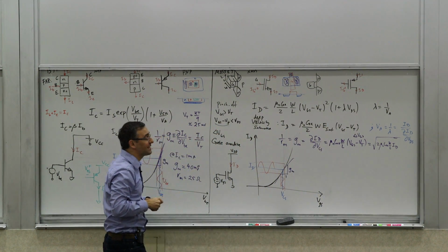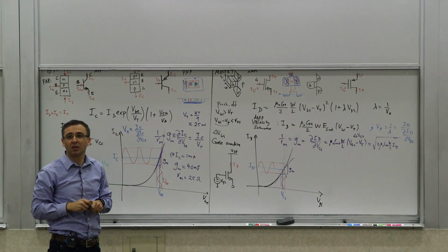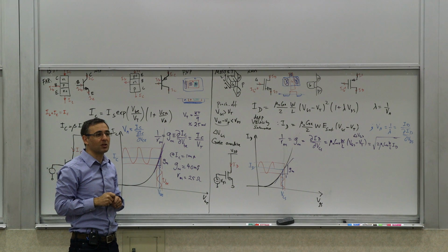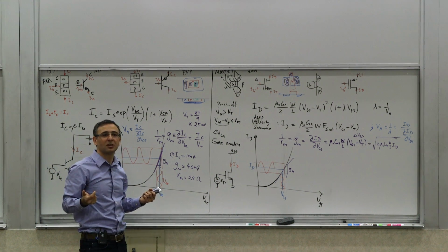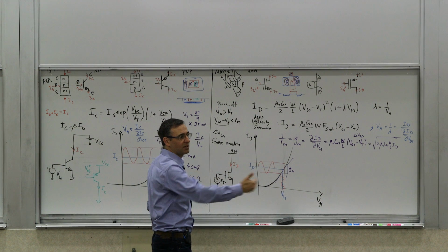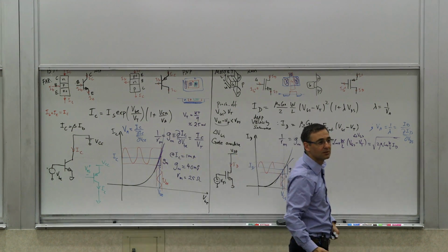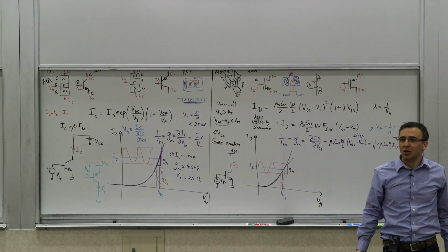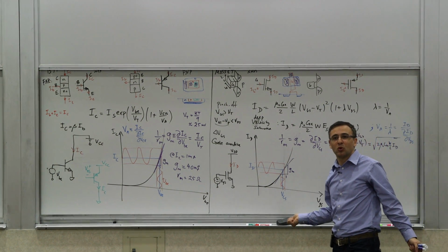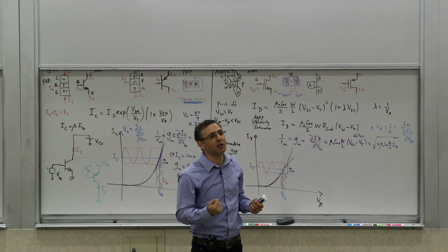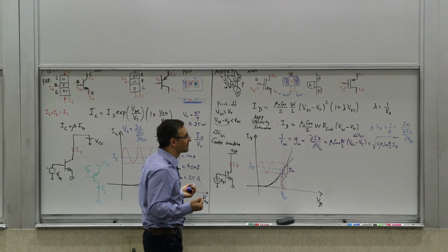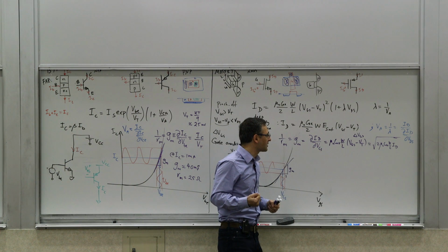So now you can see it doesn't even depend, in deep velocity saturation, on the VGS. So the operating point is not important because you're already velocity saturated. So transconductance is fixed by the maximum velocity, the saturated velocity or the saturation field that you can get. So beyond a certain point, if you get more overdrive onto it, you're not going to get more bang for your buck. You're saturated in terms of transconductance.